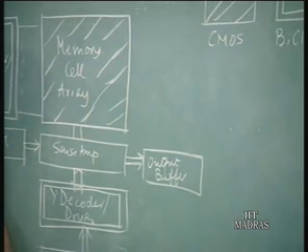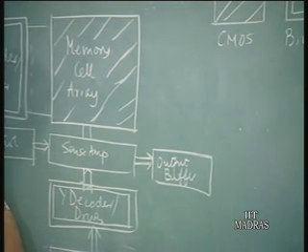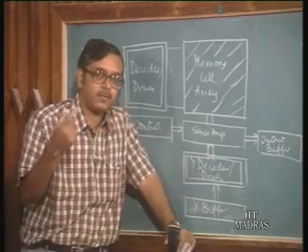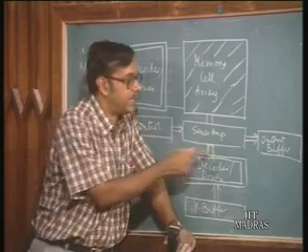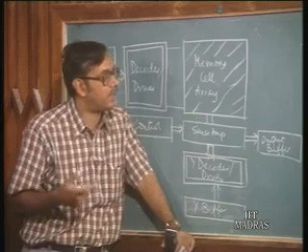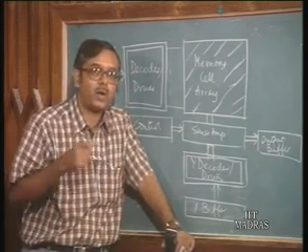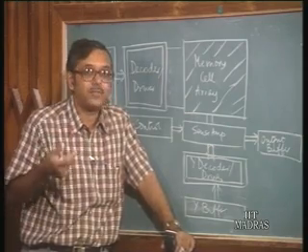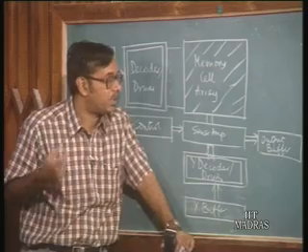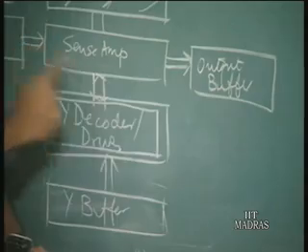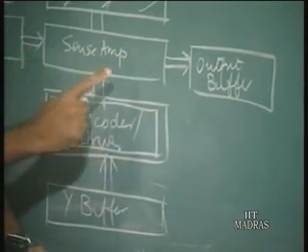Now, a small voltage can be sensed much more easily using bipolar transistors. Okay. A small difference, say of less than 100 millivolts, can be sensed by a bipolar transistor, which will result in a large change in current, which is not true in the case of MOS transistors, because you require a much larger difference in the gate voltage to be really sensed. This is because of the larger transconductance in bipolar transistors. So, bipolar transistors are generally used in these sense amplifiers.